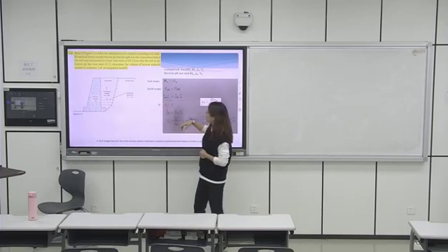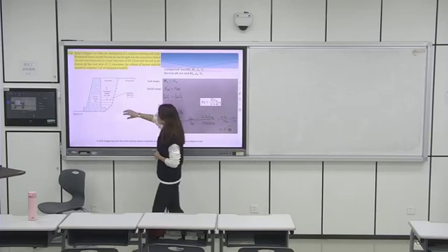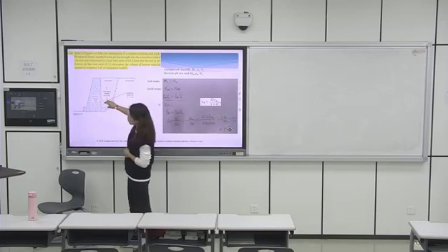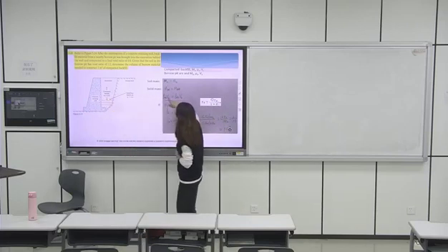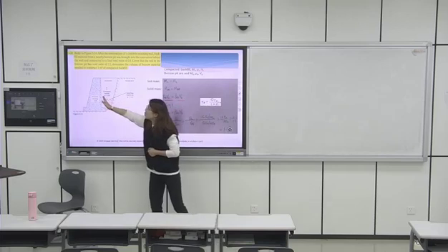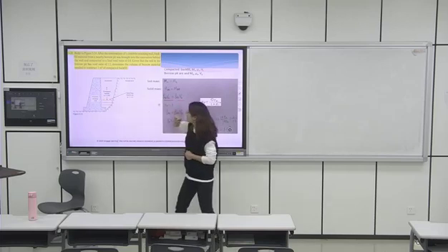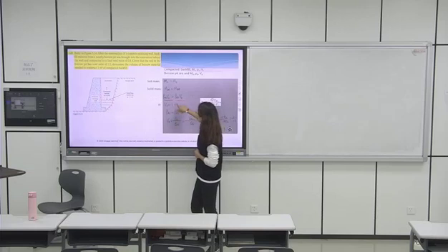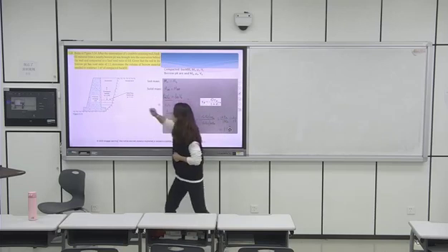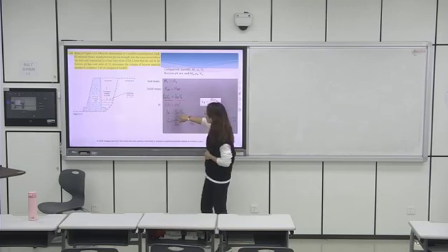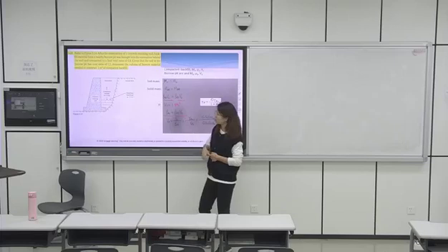If we want to compact the soil into 1 cubic meter in here, then VC, the volume in here, is 1 cubic meter, and the density here should equal the dry density of this.